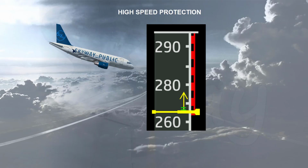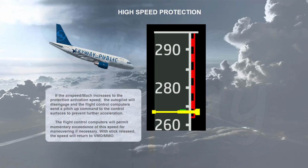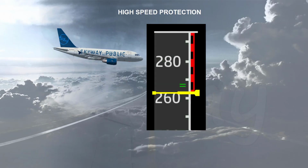If the airspeed or Mach increases to the protection activation speed, the autopilot will disengage and the flight control computers send a pitch up command to the control surfaces to prevent further acceleration. The flight control computers will permit momentary exceedance of this speed for maneuvering if necessary. With stick released, the speed will return to VMO/MMO.